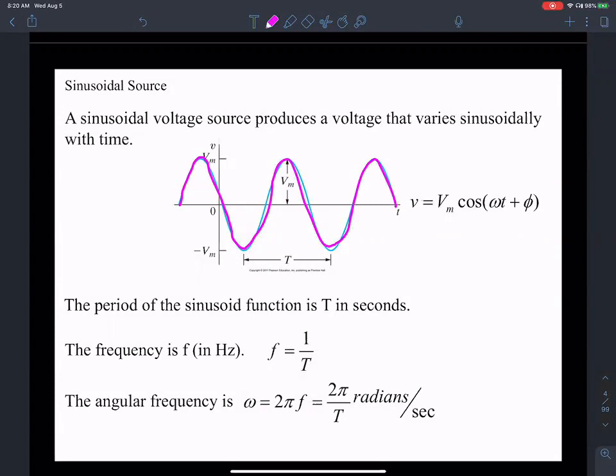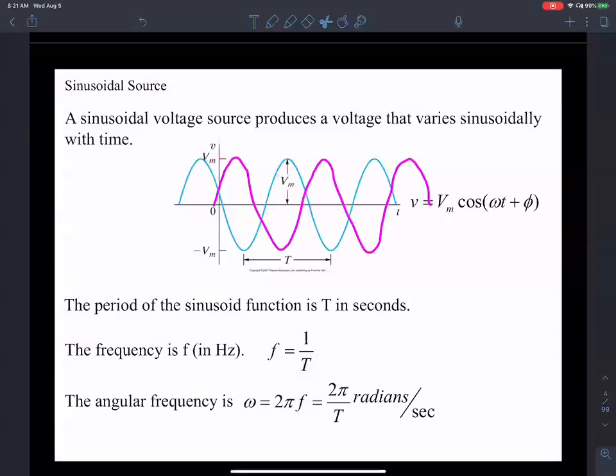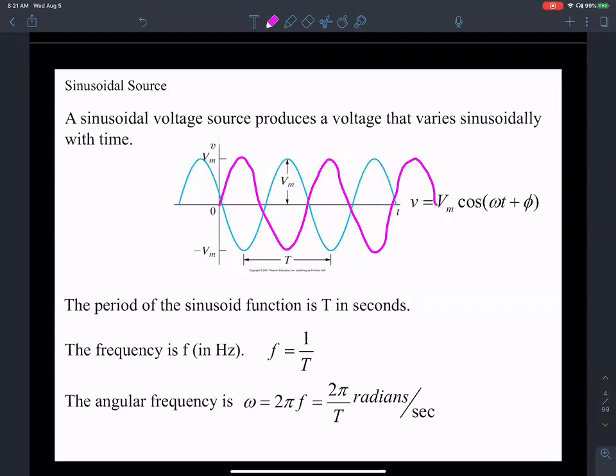Now from what you know from your trigonometry, how is this different from a sine wave? It's shifted, thank you. So the sine wave, that guy is a sine wave. So this is sine omega t, and you notice that this sine wave is beginning at the origin, and then there is an amplitude Vm corresponding to that. So the bottom line is sine and cosine waves have the exact same structure, except that one may be a time shifted, phase shifted version of the other.